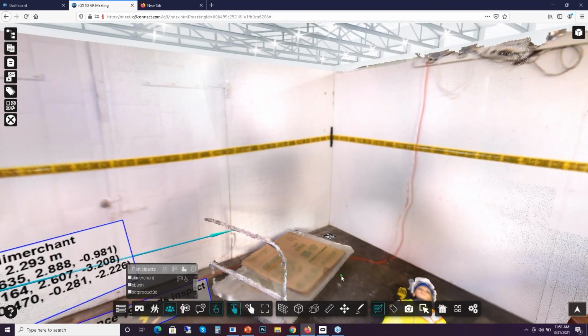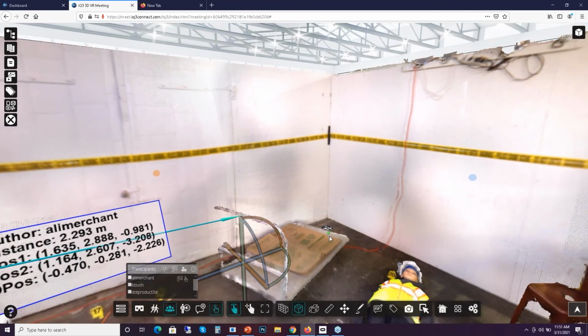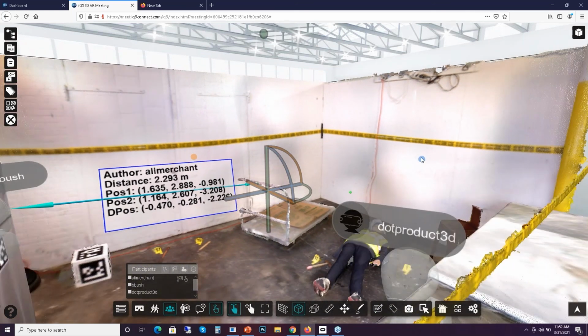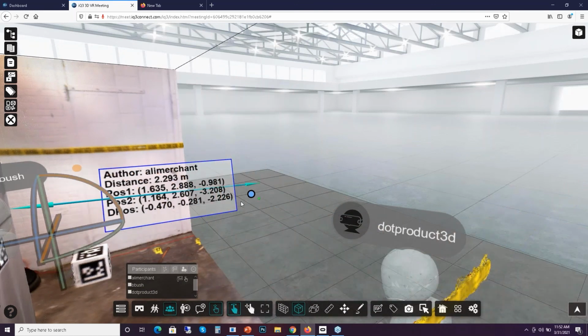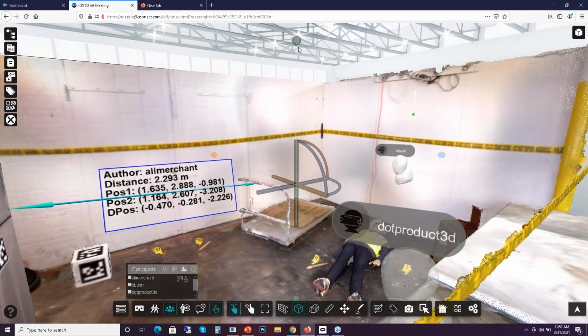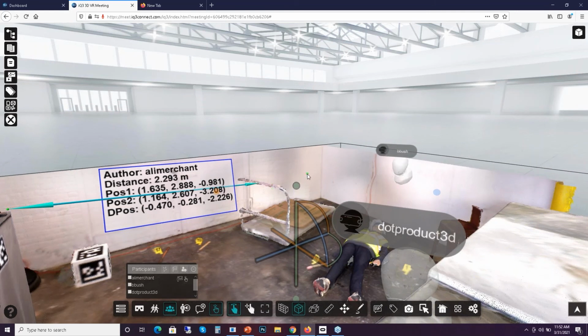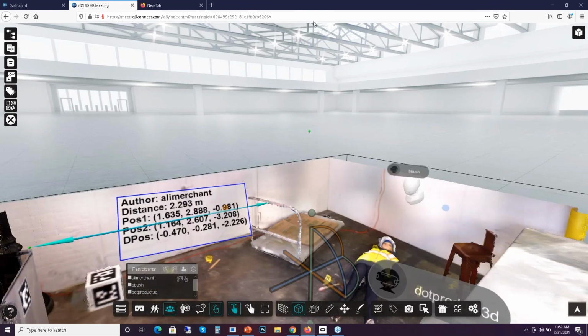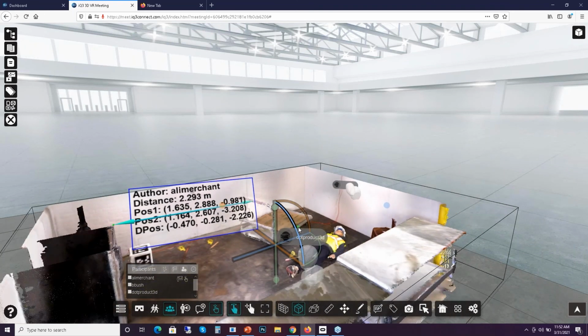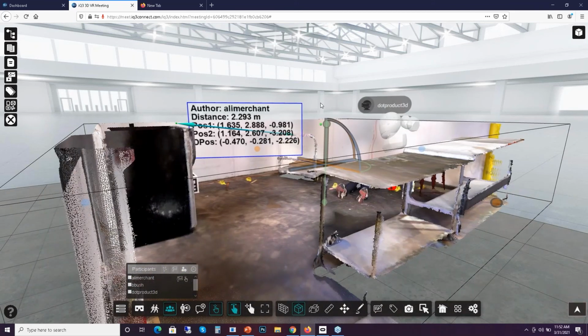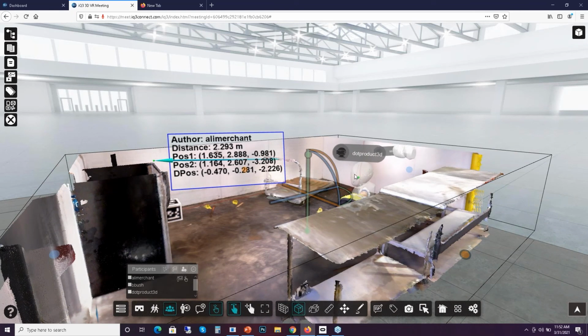With that, we have other capabilities as well, such as viewpoints, which allow you to save a complete walkthrough, creating tags, and we also have a very powerful clipping capability that I can show you here, where you can actually clip the point cloud and focus in on exactly what you may be interested in. So I'm actually clipping the point cloud dynamically, and everybody in the meeting can dynamically see the clip plane. So you can remove excessive clutter and really focus in on what you're interested in. So as you can see, Billy is down in the meeting space, and I'm just going to step back and take a bird's eye view of the scan. And I can also see that Chris is also in this meeting space.